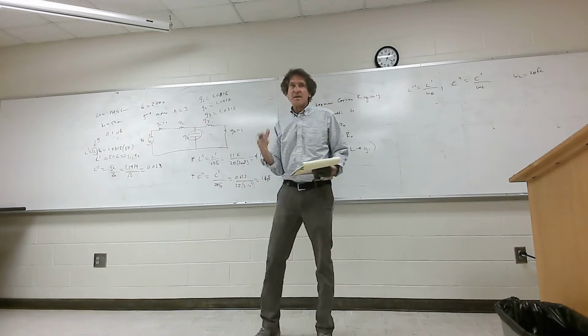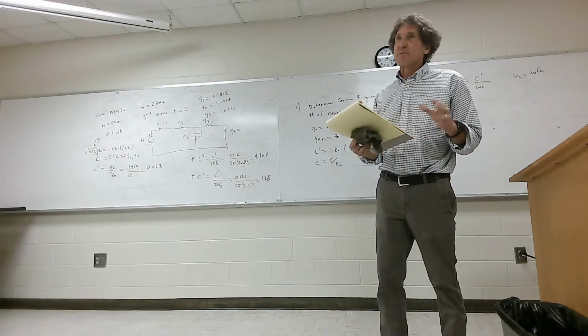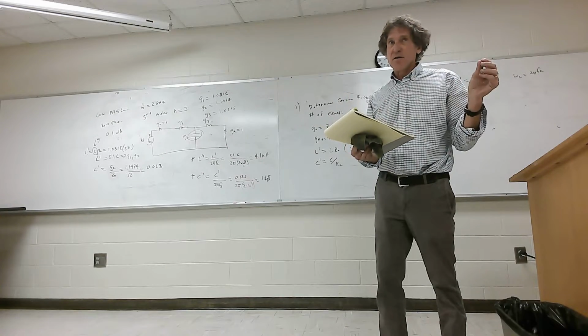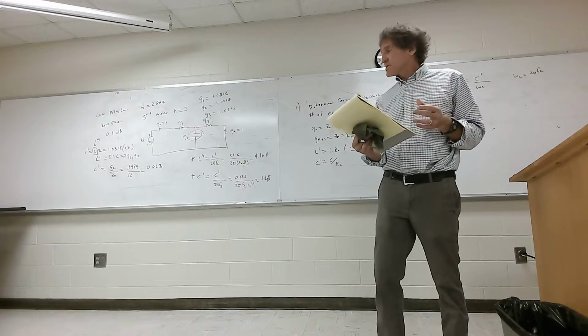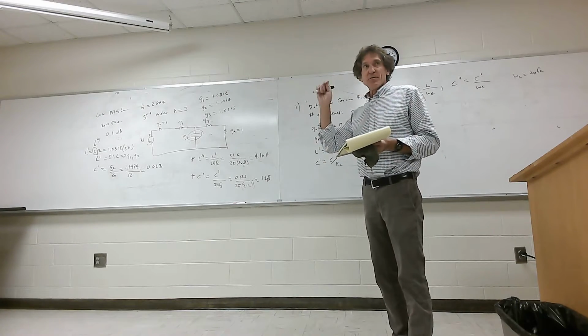I'm going to make one comment. That's a very small capacitor. They'll make them small, but you have to realize that if you ever do a filter design, your lead length there can change that substantially. So you have to make sure. Usually, when you've got something like that, you want to build in something that can tune it.